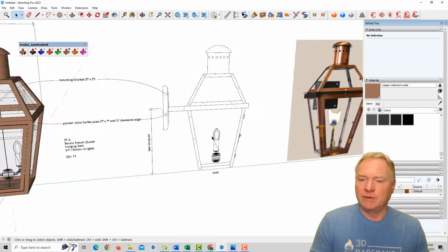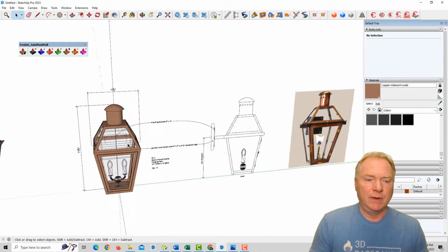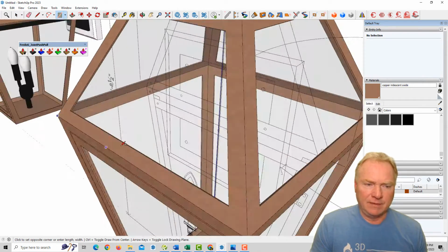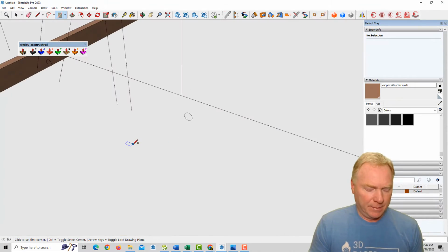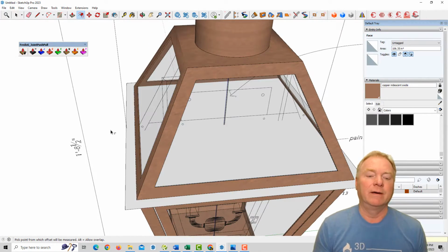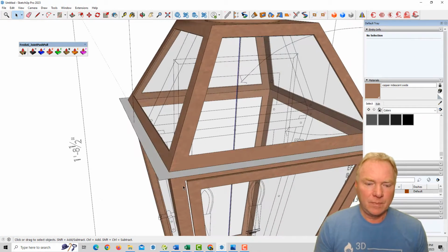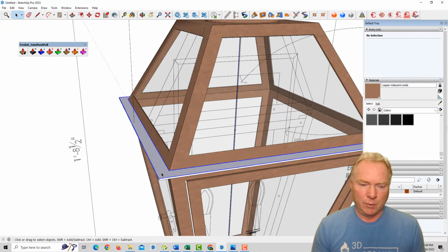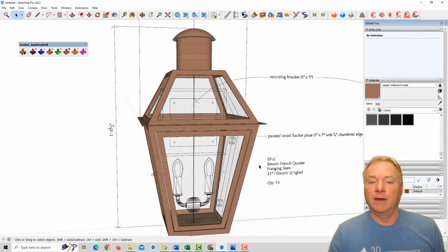All right, so the next thing I'm seeing here is there's like a horizontal flat metal strip going around this perimeter. So I'm going to draw a rectangle from the corner of there to the corner of there. But I'm going inside. I'm going to use F for offset, clicking one time, and I'm going to come to the outside, 0.5, and enter. I'm going to go back inside here and get rid of this face that I didn't need. I'm going to pull this up 1/16, triple click on it, texture it, G to group it. So now I'm getting all these pieces coming together.